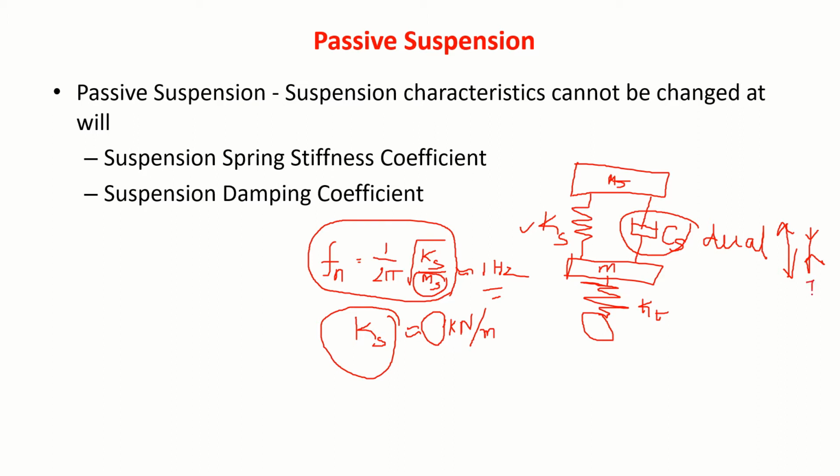I think this is correct. Jounce and this is bounce. Okay. During this stroke, we'll have a damping value of say 0.2. This will have a damping value of 0.4. But let us see, depending on the condition, even the damping value must change.